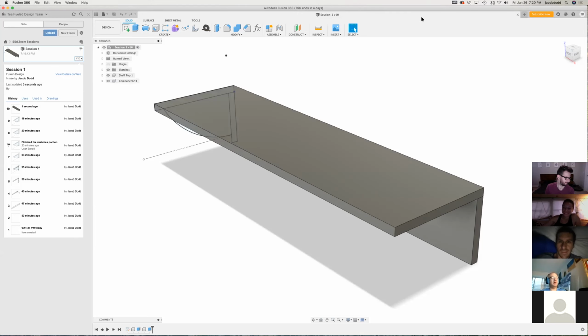What you end up doing is I would measure out one piece of aluminum extrusion. I had like 10 of these pieces to cut at this length. I do this with all the different boards that I cut with the miter saw. If I have multiples to cut at the same length, you measure out one, cut it, and then clamp it to where you cut it.